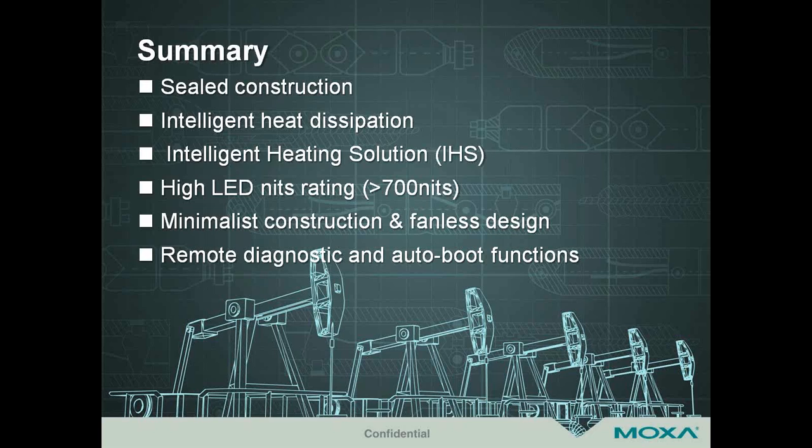Well, most of it's going to have to do with being internally sealed. So essentially anything that can create a fire, intrinsically safe is the buzzword here. Any electrical communication within the unit shall not and cannot be able to ignite any external gas. So it needs to be tight as a drum. That's as important or more important for oil and gas networks as it is the other way around.